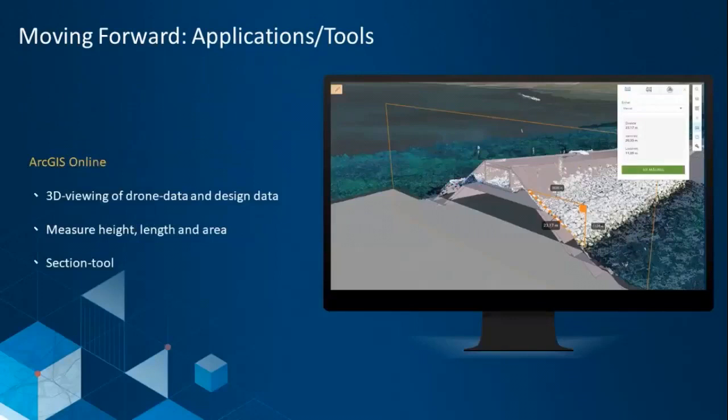So what applications are we looking for? The obvious application is seeing 3D design data and 3D drone data together in one place and in a web viewer. There is value in not having to imagine the site as you do in the 2D views of the orthophotos. Another application is the ability to measure height, length, and area in the 3D scenes in ArcGIS. And as shown in the picture, it's also possible to make sections and do measurements in the sections.